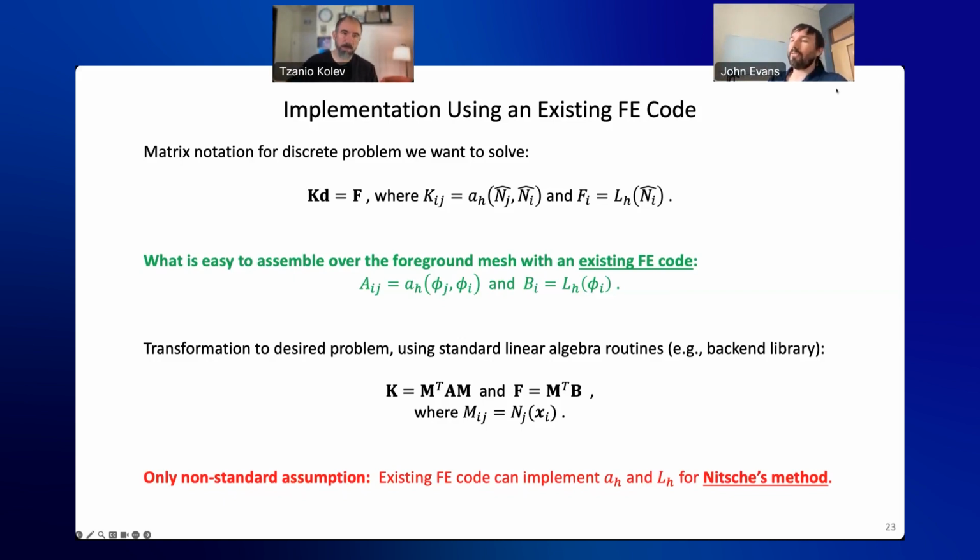So multigrid for immersed methods in general is actually a difficult problem, and it has to do with a couple of things. That small cut cell problem that I mentioned rears its ugly head and provides all sorts of pains. This is actually related to the smoother rather than the coarsening of the space.